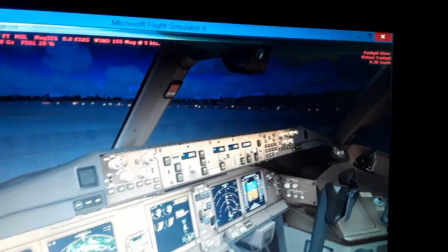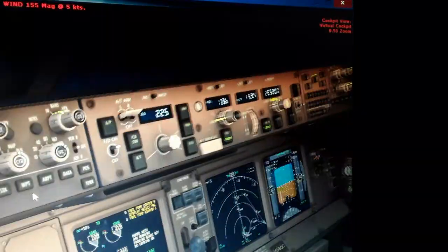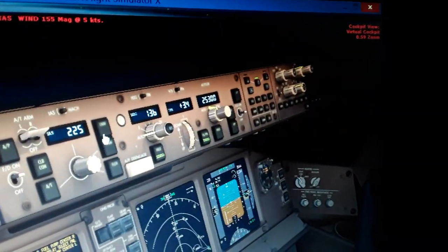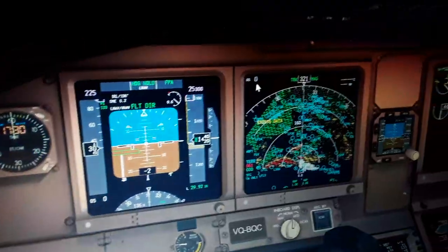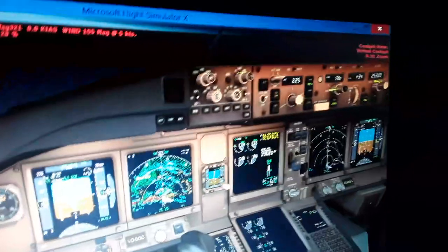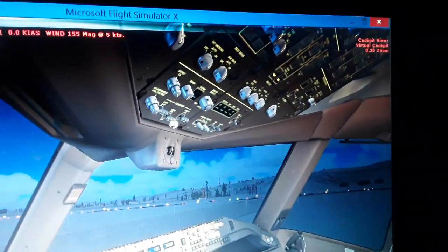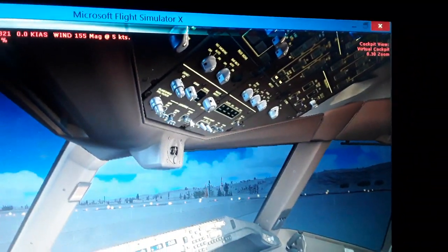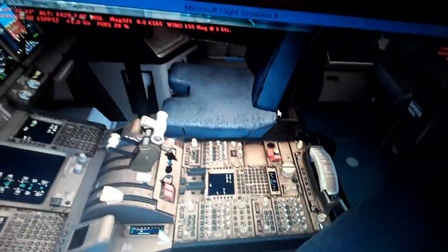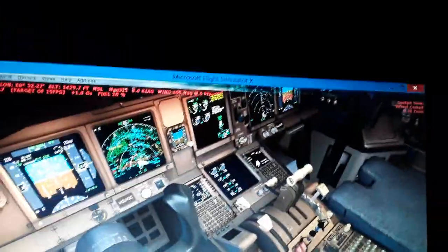We have like 4 or 5 minutes and plus 18. So this is the autopilot set, this is the display set. We have some more modes. Use the lights here. So advance the thrust levers a little bit, and disarm the parking brake and go.